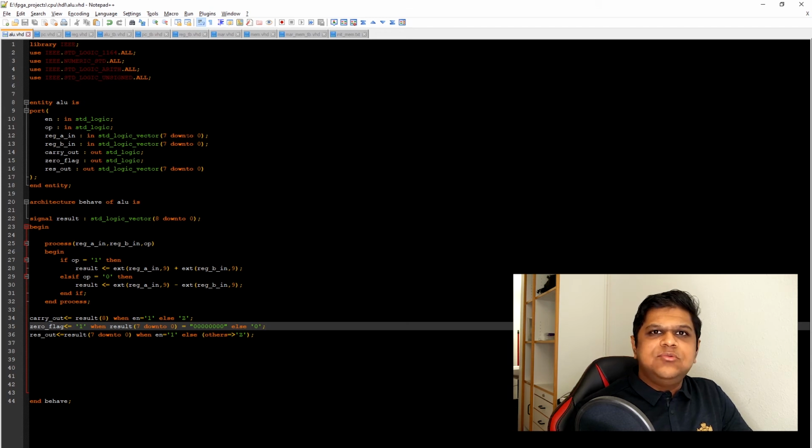In our CPU we have a common bus, and all the registers, the ALU and the control unit are connected to our bus. So if 2 different components try to output a value to our bus at the same time, it will go into an unknown state. For that reason we have to make sure that at any given time only one component is outputting to our bus,